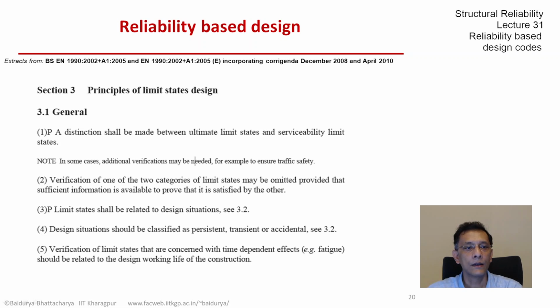Finally, more details on the type of limit states to be considered are spelled out. So we see specifically that ultimate limit states and serviceability limit states have to be considered. Not only that, the designer also needs to worry about not only the operating condition, but transient situations and accidental situations as well. So that presumably includes the construction phase as well.